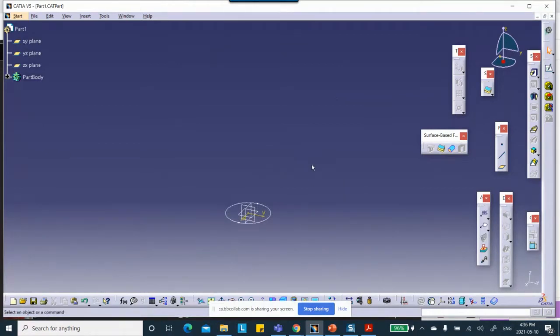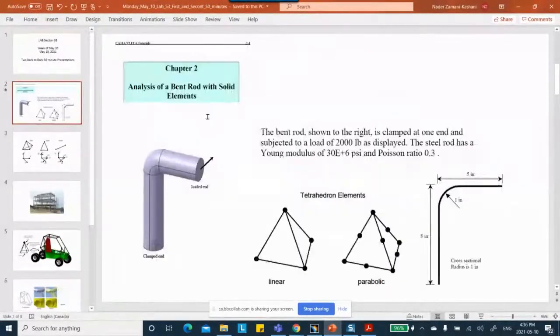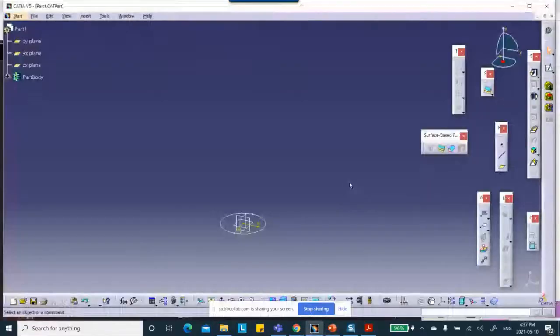Okay, now notice that on purpose, I'm going to center it at the origin. The more you're confident about your CATIA skills, the more of these special things that I say you can skip, okay? But I put it at the origin. Now, I want to draw the center curve of that object. And the center curve of that object was right here. Where is this? This guy, okay? 8, radius 1, and 5. Okay, so let's do that.